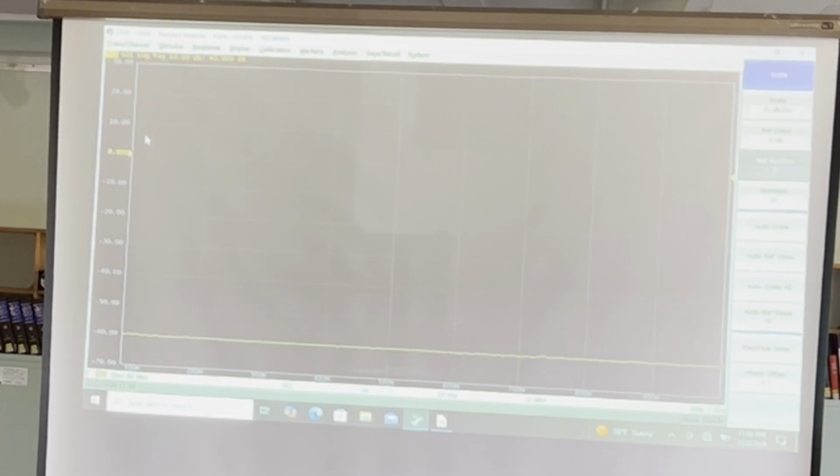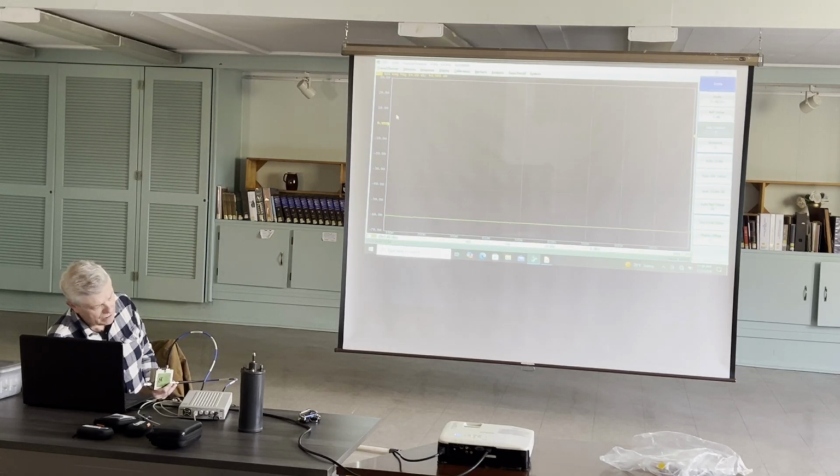That's the loss across that frequency spectrum, from 80 megahertz all the way at the left, all the way over to the right. Notice how flat that is? That's equal loss. These couplers are manufactured this way. This is what is called a compensated coupler.